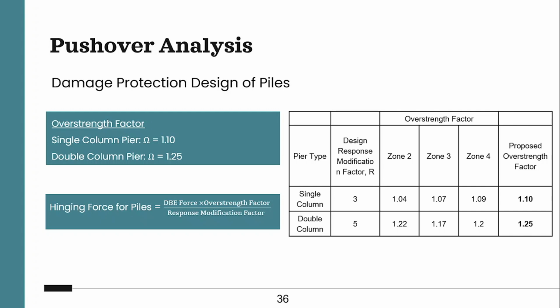So we have to provide a hinge length, as this is a kind of distributed plasticity model. That hinge length has been taken to be 0.5h, which is a common hinge length used for different structures. Here h stands for the maximum dimension of the element. With that fiber hinge analysis we calculate the ratio of the maximum moment and the design moment, and finally find the overstrain factor.